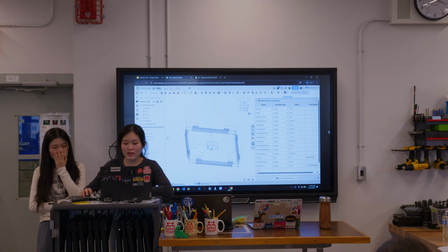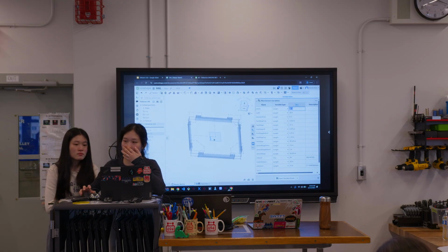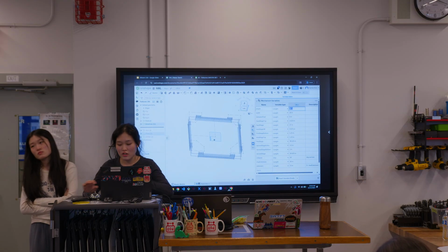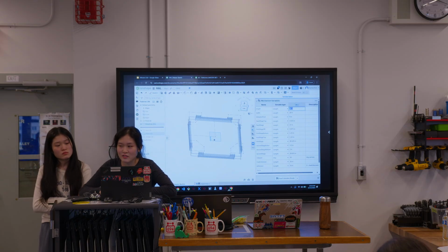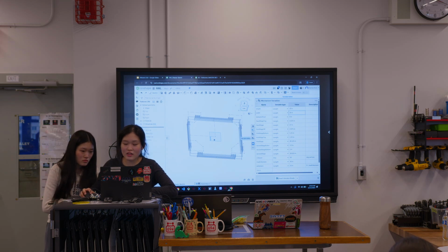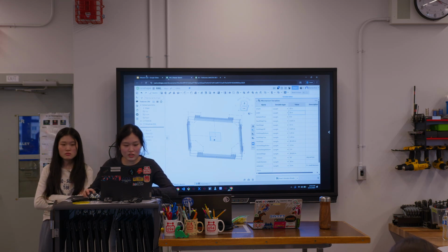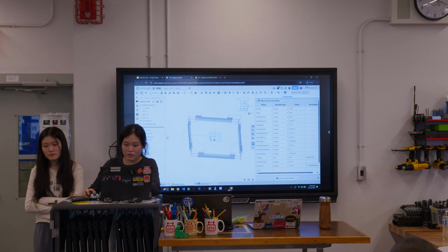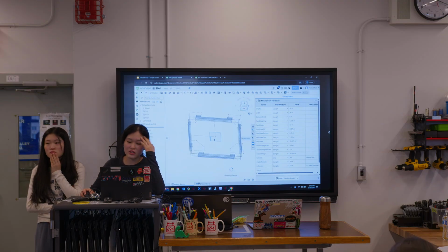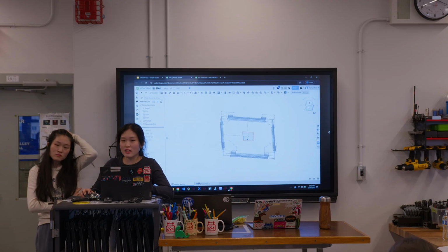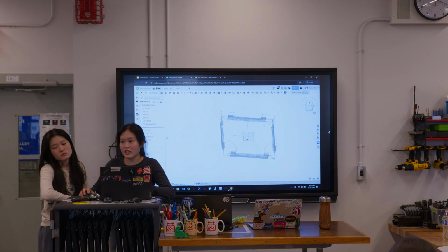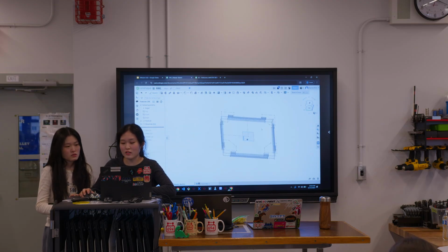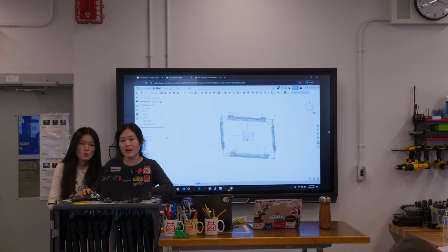So that's why we were trying to adjust the dimensions, which is why it was a lot easier for us to do in Sketch. So let's say we realized I want the drivetrain to be 29 inches in length. Let's just change it. It's a lot easier to change with Sketch, because if you just see, a second ago this is 28 inches, and then we could just easily change it to 29 inches. So it was a lot easier to change the dimensions through sketches rather than assemblies when we need to make quick changes, which is why it also really helped us.